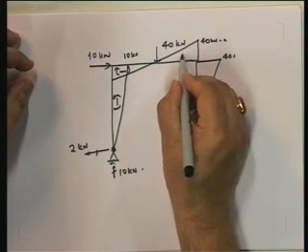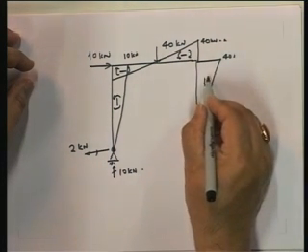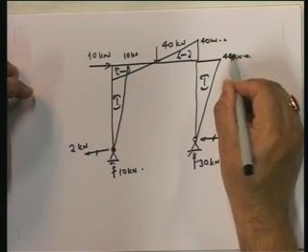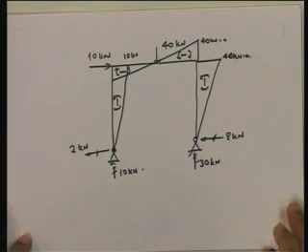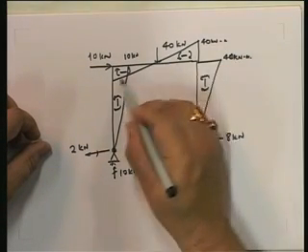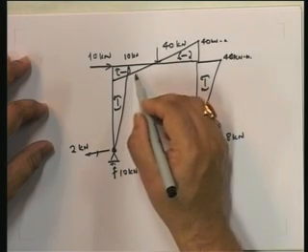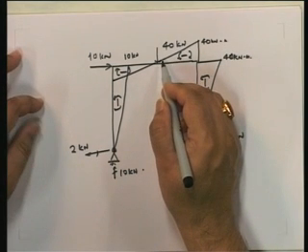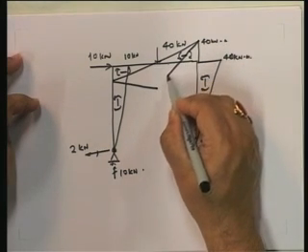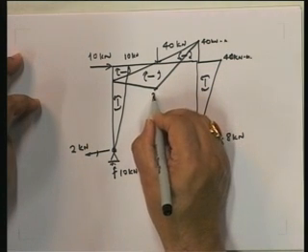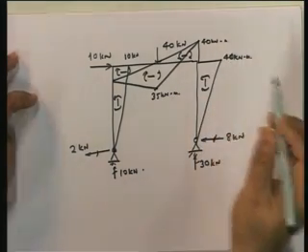Here this is in this fashion, here it is in this fashion, here it is in this fashion. And these are the member end moments that you already have. Okay, so this is your bending moment diagram. This one is this way, that is only due to the load, but there is a superposition over here, and that's 50. So this is going to be 10 and 40. So at the center, it is going to be equal to 40 minus 10 upon 2, which is 15 in the middle. So this is going to be 35. So it's going to go like this and like this. Okay. So here I have this, and over here this is going to be 35 kilonewton meter.